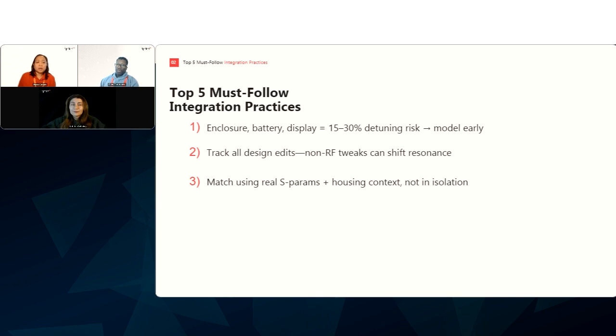All right. I'm going to jump to the next one so we can go to the next part of the webinar. So we have here: design for a plus or minus 10% tolerance for component drift, PCB stack-up variance, or aging effects. If your matching only works on nominal, it's not robust. So Sifiso, maybe I'll ask this question to you, because we had a chat before about this 10% allowance, right? Do you agree with this? And if not, how big should the margin be?